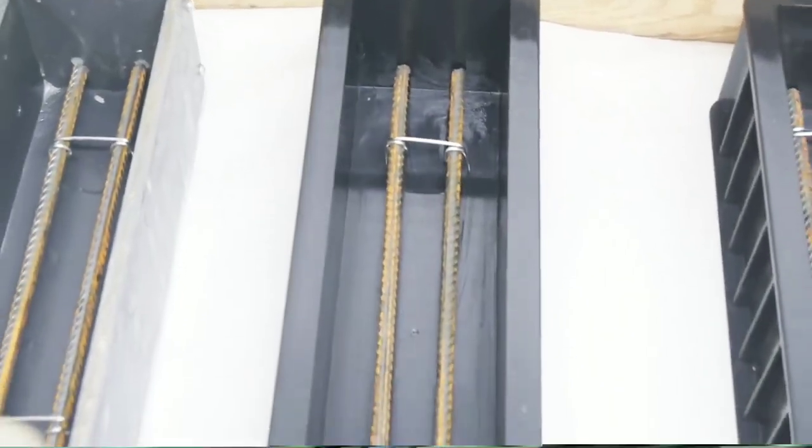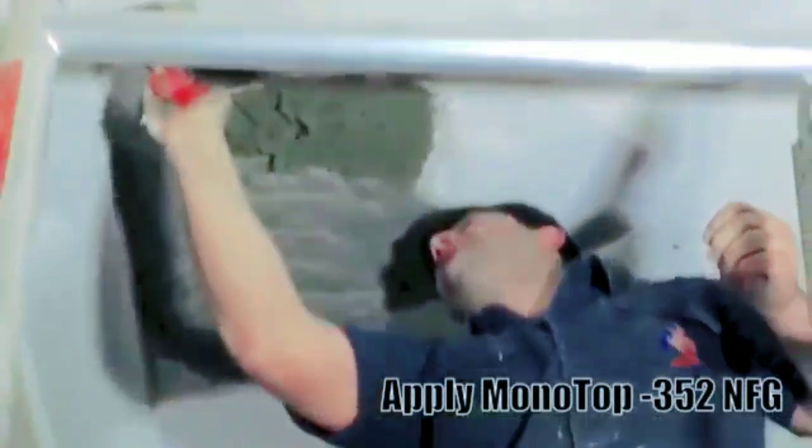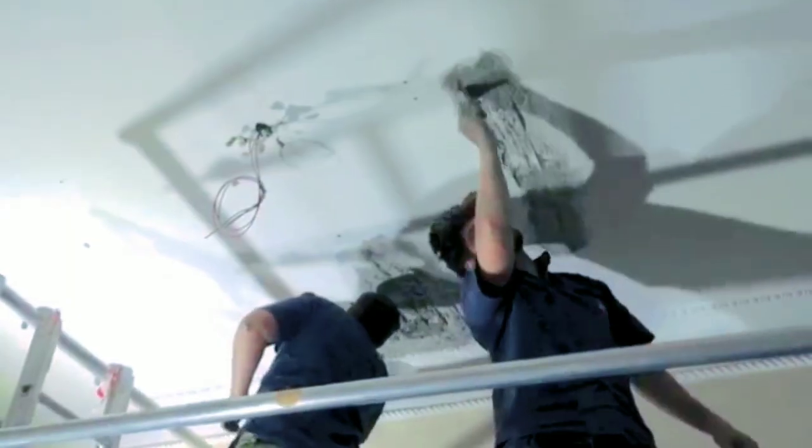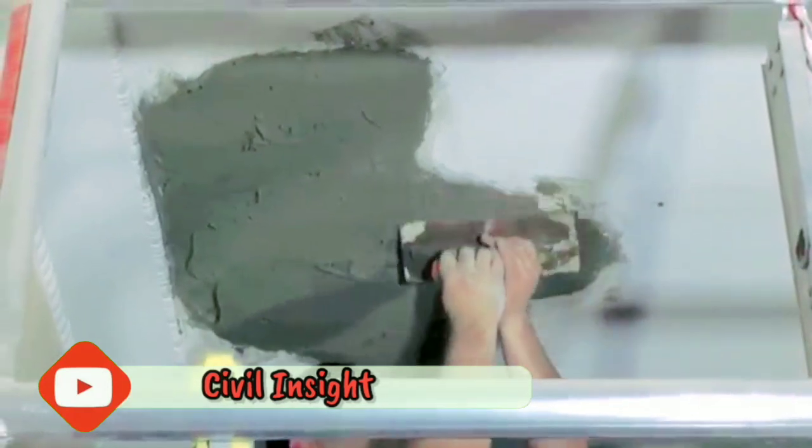Another way of treating concrete cancer is to repair all minor cracks and damage to your concrete as soon as you notice them. This is especially important in exposed areas, as water getting into the concrete through the cracks will cause the problem to worsen extremely rapidly.